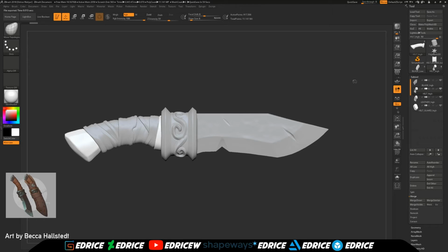But that's something that is outside of ZBrush, so it's something you might want to do. You could export every subtool inside of its own OBJ, then import them one by one in the external package, but it's just a lot more work. So using FBX instead of OBJ will help you export all these subtools.